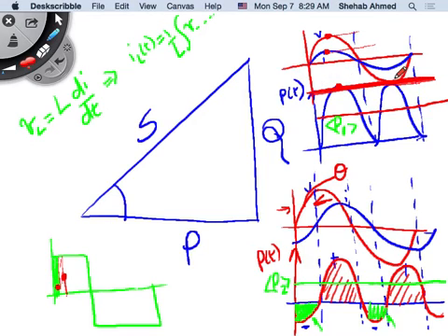correct? So for the same voltage and current ratings of a cable, if I put DC through that cable versus I put single phase AC through the cable, which will be able to transfer more average power to a load? DC, right? Do we agree?